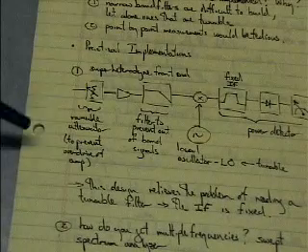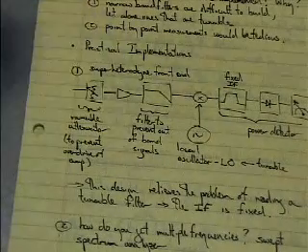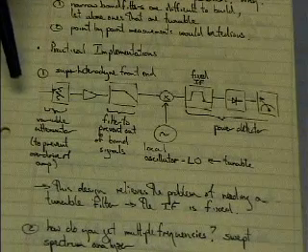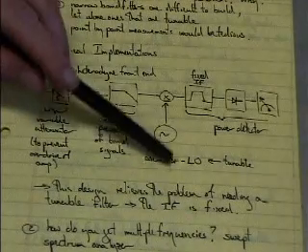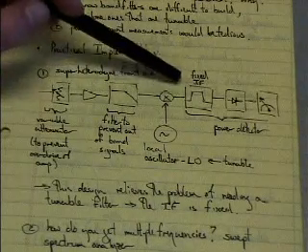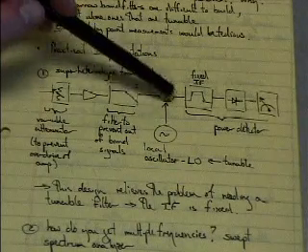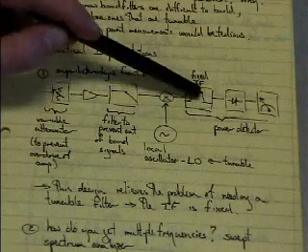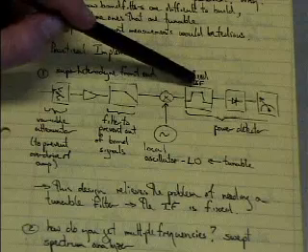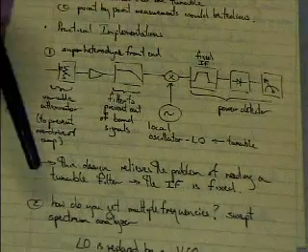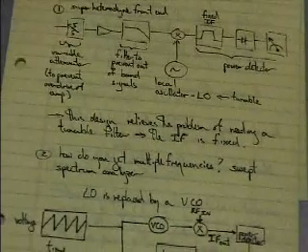Okay, so this particular design here allows us to create a practical spectrum analyzer, one that we can adjust the frequency of to look at particular signal components. Okay, we can set up a very narrow band filter, and we only have to design one of them, and this can be fixed at the intermediate frequency, or the IF. Okay, well, how do we get multiple frequencies?